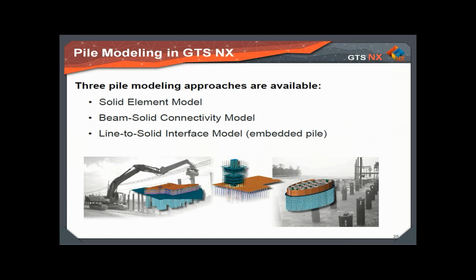When we come to GTS NX, we can model piles with three different approaches. Actually, in general, in a 3D numerical tool, you should be able to model your piles as a volume element, and you should have a proper interface around it to be able to capture the interaction between the pile and the soil properly. So this is a basic ingredient you should have. In GTS NX, we can do that.